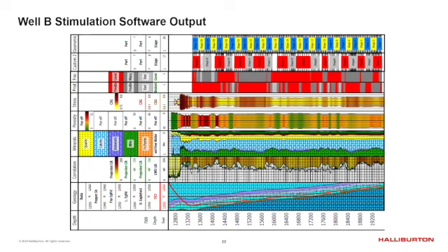And it's always post-mortem, right? When we're dealing with stuff, we're always dealing with the well that's delivered to us. But even post-mortem, I can start working with my driller to do a better job on the next well at least, and understanding what the limitations are with this one. And if the drillers understand what the problems are, you have a much better chance of correcting that going forward. So we eliminated 12 stages from this well.